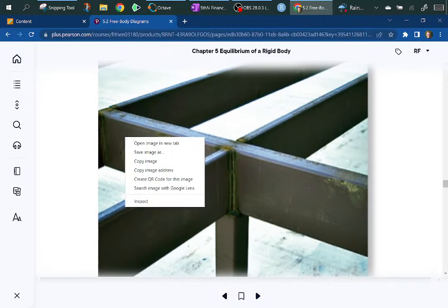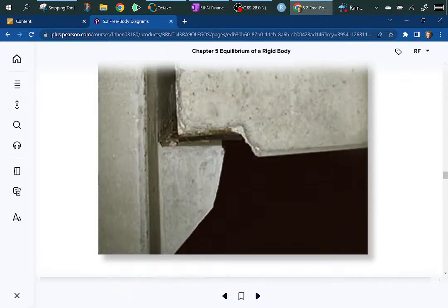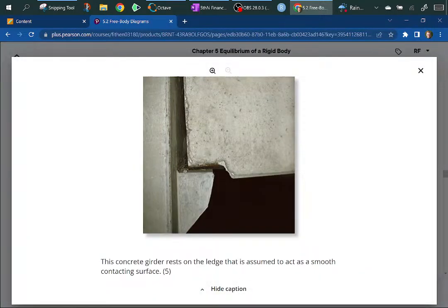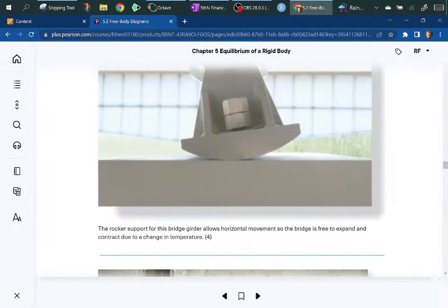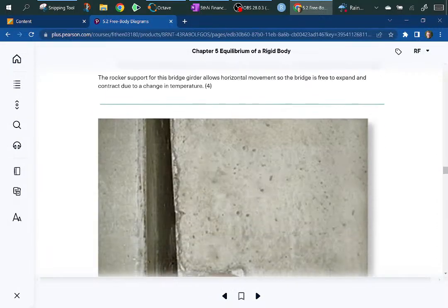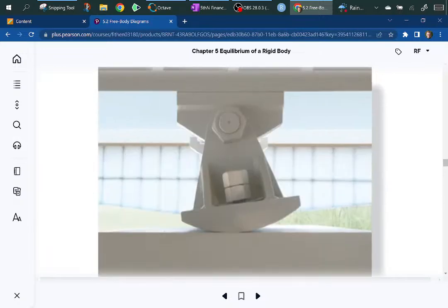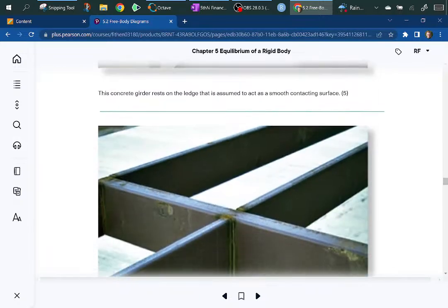You'll see more welded supports. In highway structures, you might need the structure to be able to slide because of the temperature change. In that case, the rocker would move because of the temperature change.